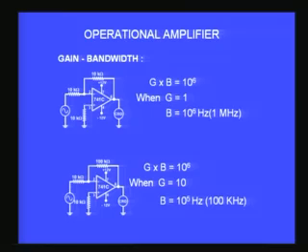So with this, let me go to the table and show you a demonstration of two amplifiers, one with a gain of unity and another with a gain of 10. Both I will apply the signal and try to observe what happens to the output. I will show you that the output starts decreasing at a particular frequency. I will almost take that as nearly the cutoff frequency. Otherwise one has to carefully look at the output and calculate when it becomes 0.70 times the mid frequency gain, and that will be the point to precisely choose.